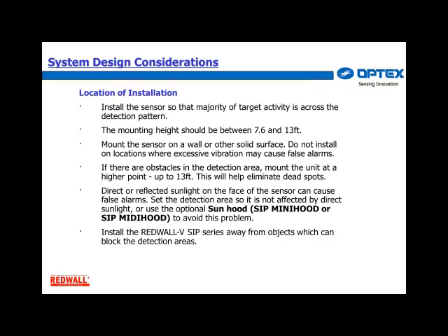Install the sensor so that the majority of target activity is across the detection pattern. The mounting height should be between 7.6 and 13 feet. And mount the sensor on a wall or other solid surface. Do not install in locations where excessive vibration may cause false alarms.